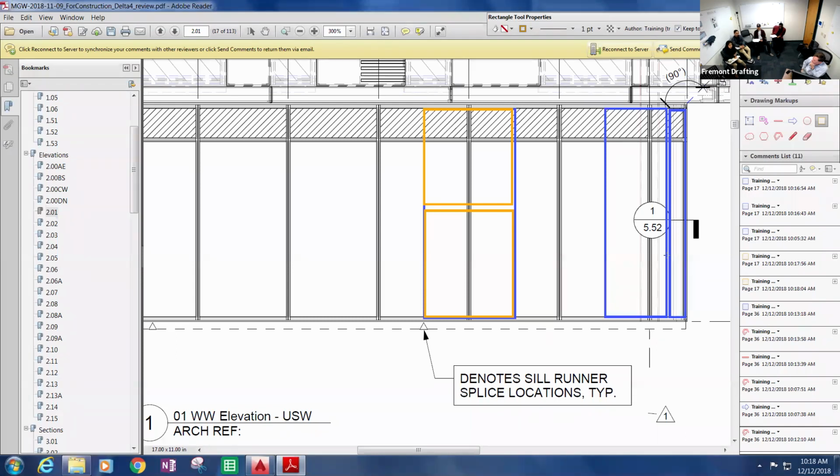So again, it's not deflection anymore, or is it also calculating deflection? Well, I was just trying to define tributary area and why we need to know what it is, in the different cases. And it does affect deflection, because that's the first one we looked at, to measure. So this blue, yeah, exactly. That's what you use to calculate the deflection of the vertical. So that blue tributary area is used for deflection of the vertical, and it's used for dead load of this anchor.